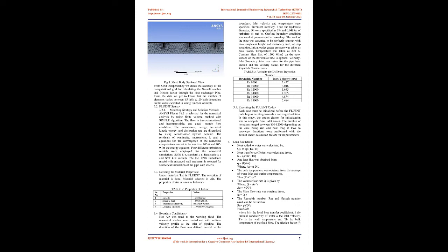CFD procedure followed. Preprocessor. Preprocessing is the input of a flow problem to a CFD program by means of an operator-friendly interface and the subsequent transformation of this input into a form suitable for use by the solver. The steps involved in this are 1. Definition of geometry. 2. Grid generation. 3. Selection of the phenomena or system to be modeled. 4. Definition of fluid properties. 5. Boundary conditions specification.